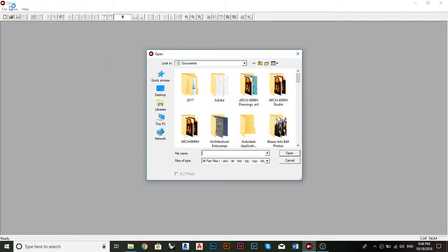Remember, ZPrint. Some of you downloaded ZEdit, but we want ZPrint, because ZPrint is the slicer software. It will read your documents via an STL document. So you want to make sure you export selected, do not save as from Rhino. You want to export selected as an STL file, a stereolithography file. And that way ZPrint will open it.